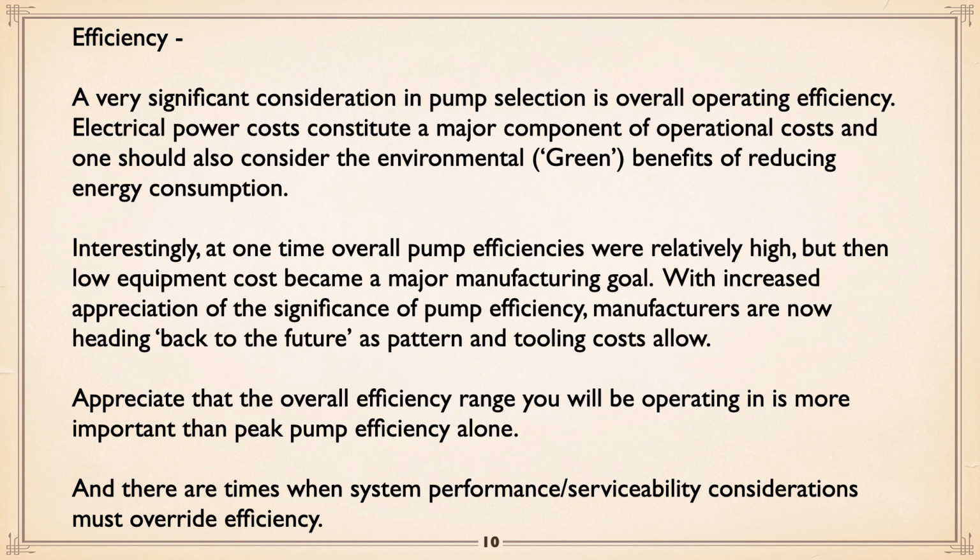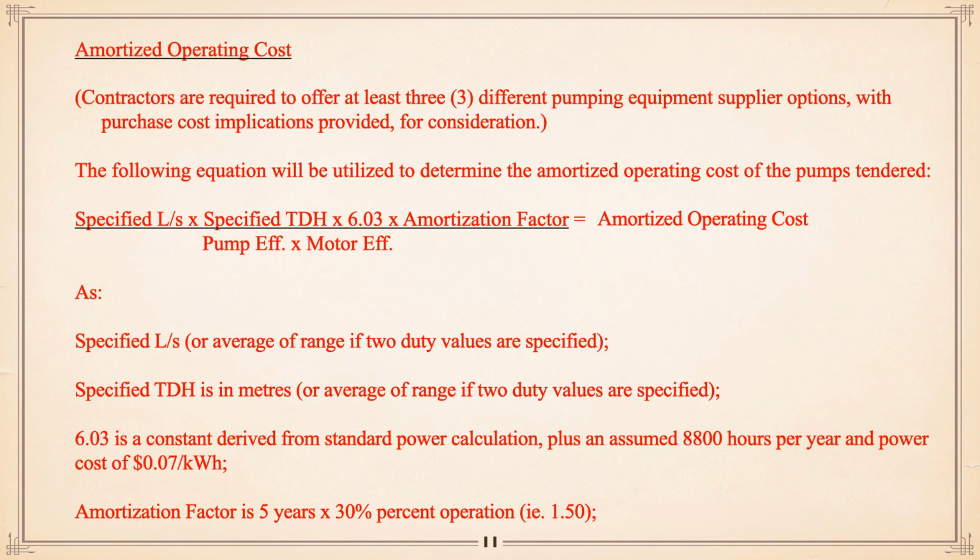They're going back to the future and pattern a lot. If you're already building a pump, it costs a lot to have the castings for a new pump, but you're seeing that trend in that direction. So everything old is new again. And it's the overall efficiency range you'll be operating in that is more important than the actual peak pump efficiency alone. And there are times when system performance and serviceability considerations have to override efficiency. It's a great pump, maybe very efficient, but if it has problems, it usually ain't worth it.